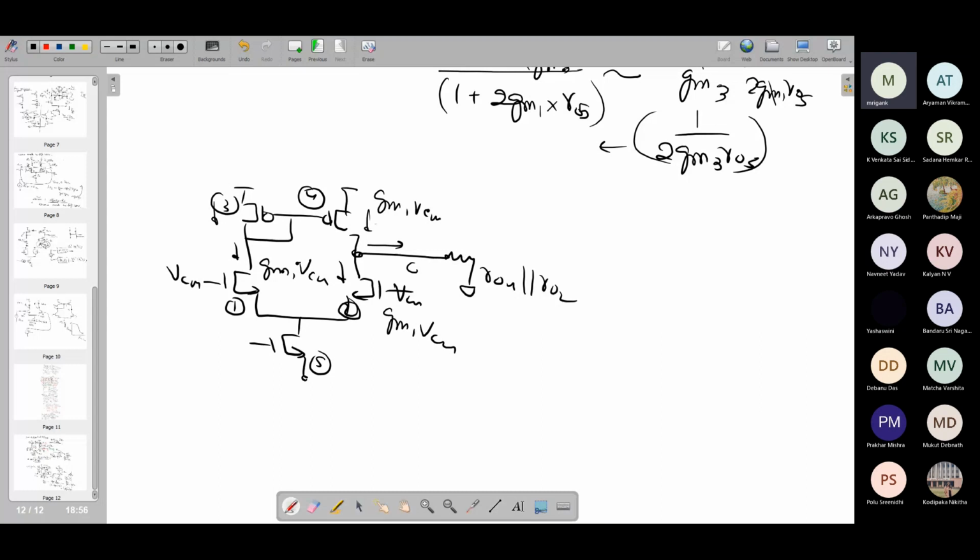That is, from the point of view of approximate small signal analysis, we can understand why the common mode gain is poor here. Of course, as this is an approximate analysis, we have not taken into account RO, etc., of the upper MOSFETs while considering current routing. There will be some RO associated here, and some current loss because of that, but we are ignoring all of that and conceptually trying to understand why this is common mode is better.